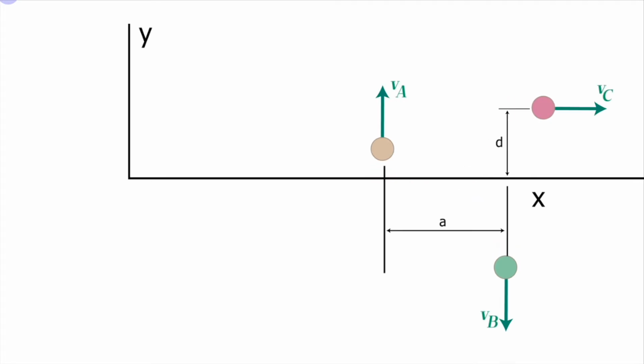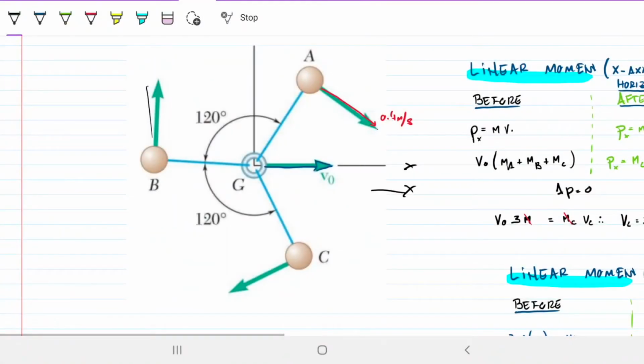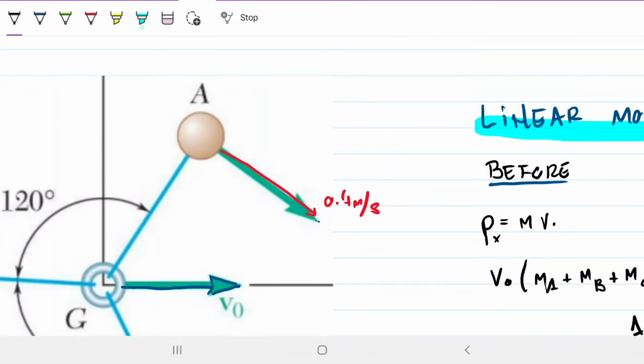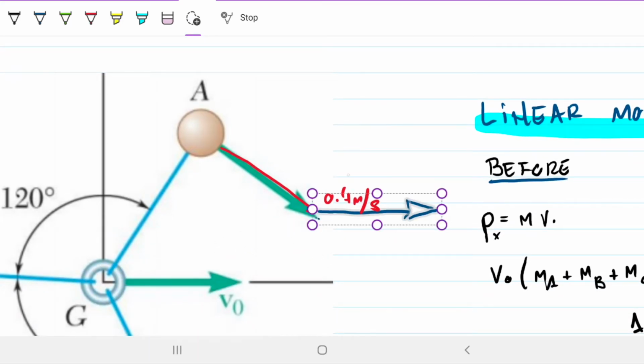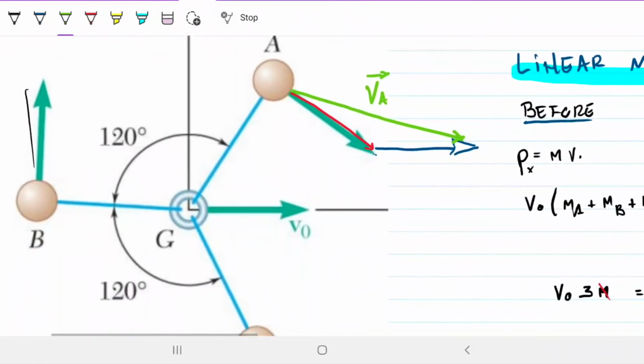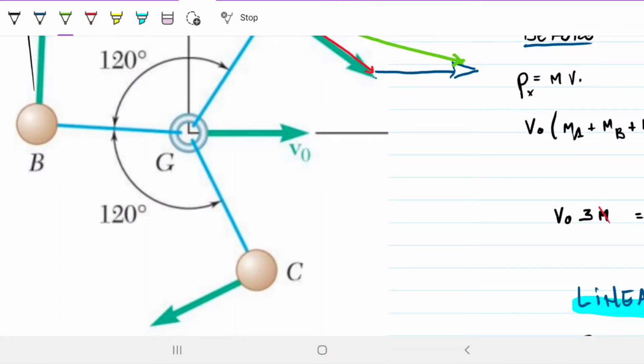Okay, so there are two ways you can go about computing this when we're doing the calculation. One way, which I guess is the hard way, is to do what we talked about before and get this vector here, place it here, and then combine the two to get the vector for velocity A, let's say the absolute velocity for A, and multiply by the mass of A. So we're going to get the kinetic energy for A, and then we can do the same thing for C, right?